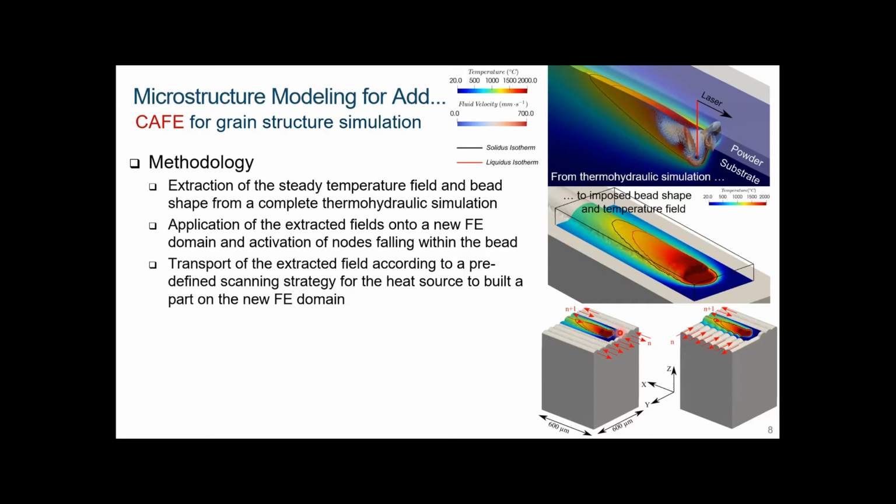For instance, here you recognize the plus x, this is the x direction, so you go to the plus x, minus x directions, so as to build layers, and you can do many layers, or you can here have this cross layer directions for the scan. So here you have plus minus x, but at the layer below you have plus minus y direction for the scan, and of course you change that with the cellular automaton method to predict the grain structure.